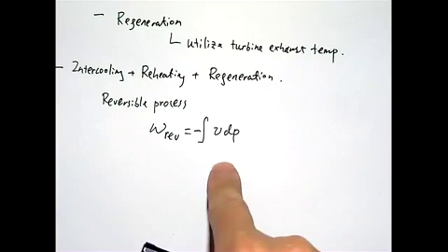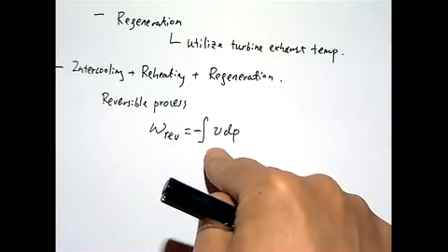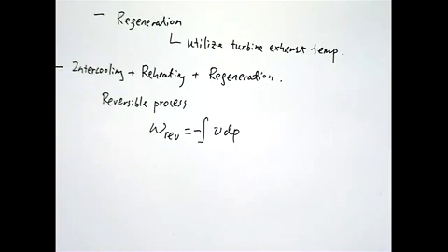So the purpose of the intercooler is to keep the temperature low. Even though going through an isentropic process the temperature goes up, you want to keep the temperature always low. You take away some heat from the system so that the volume stays low, and you can minimize the work done at the compressor to the system.